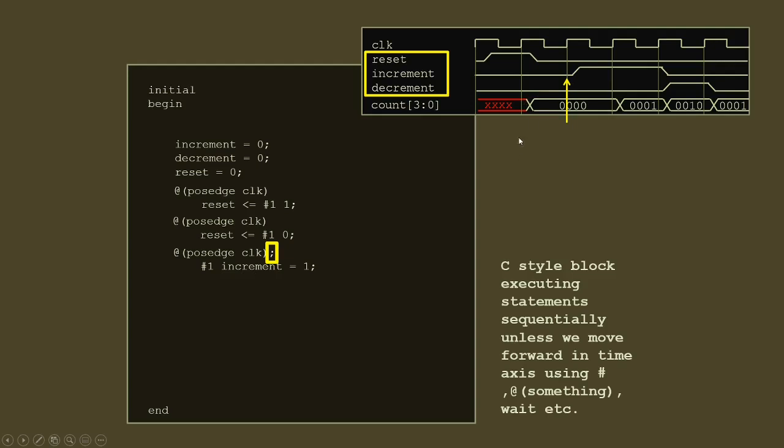So that will have exactly the same effect as if I had written this kind of a statement or this kind of a statement. If I hadn't used the semicolon and had used a non-blocking statement, it would have the same meaning in this case. But this syntax I normally prefer. Then I want to span 2 clock cycles instead of 1.